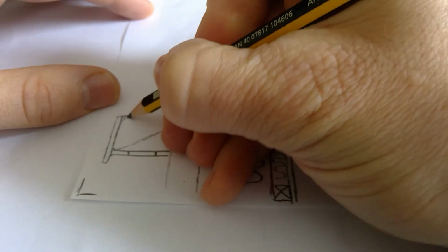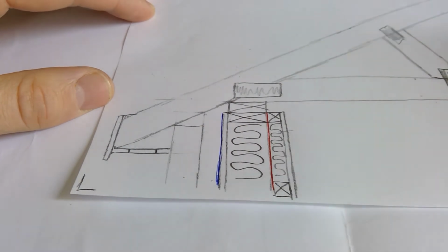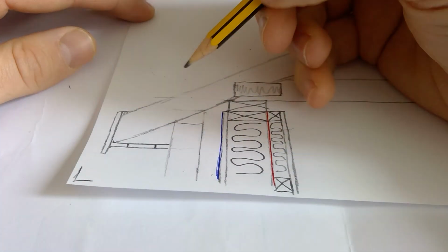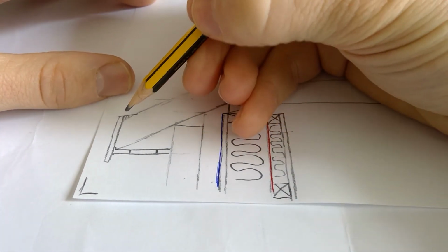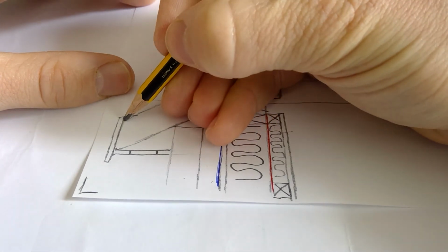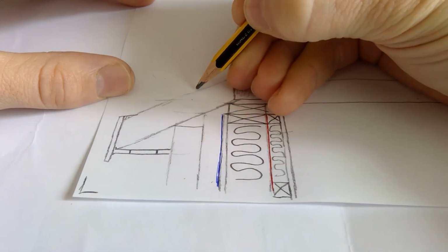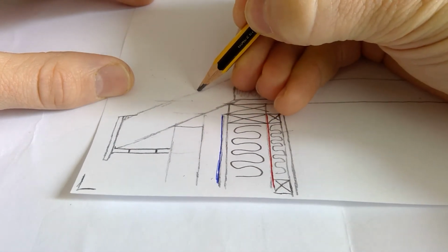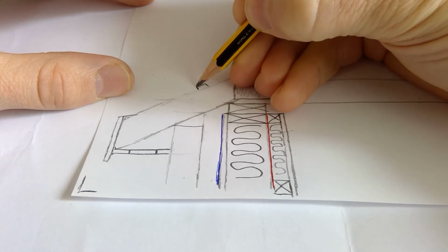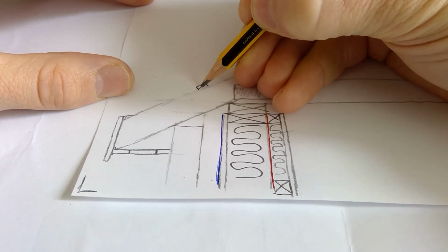Tilting fillet here. Alright, now again, slates, tricky. A 700 millimeter is the standard size for a slate, so our battens are going to be half of that, 350 apart. From this point, I measure 35. Draw a batten, 50 by 35.